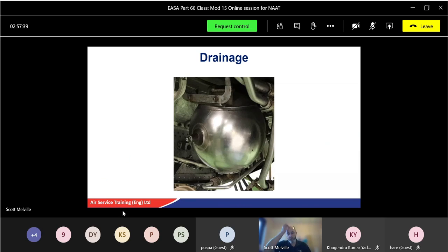So the drain tank itself, the fuel's drained, sometimes emptied during the next start cycle, so it'll go back into the exhaust. Okay, it creates a depression and allows it to go to atmospheric pressure and push the fuel out of the drain into the exhaust, and it will hopefully ignite with that as well. There's not usually too much in there. All right. Other types, you might have generally more modern engines. The drain tank is emptied by a fuel flow from a post-LP pump source to the ejector pump at the bottom of the drain tank, and then passes off to the inlet to the LP fuel pump. So it gets reused again, it gets burnt off, so it's quite good.